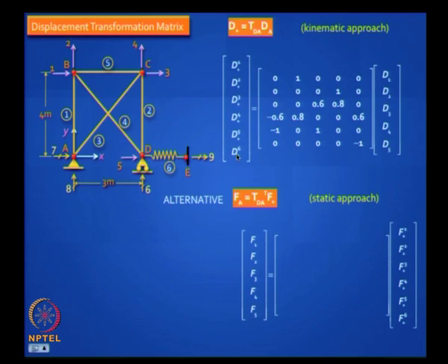The element, what do they refer to? What does D1 star refer to? Axial deformation. It is just the elongation in the element 1. This has only 1 degree of freedom. Is it clear? And so if you move the structure, the joint displacement one at a time, it is going to cause elongations in the different members, and we are trying to figure out what these elongations are.